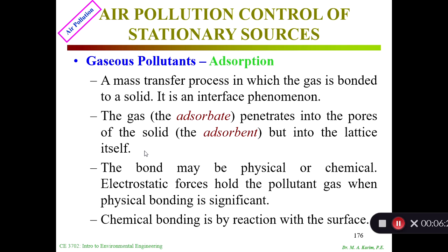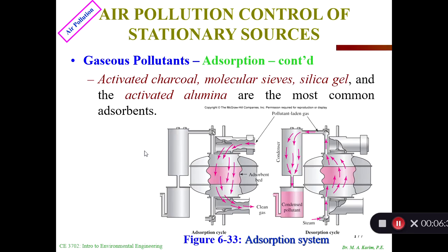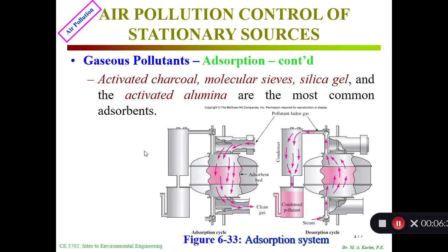The bond may be physical or chemical. Electrostatic force holds the pollutant gas when the physical bonding is involved. Chemical bonding is by reaction with the interface, if there is any. Activated charcoal, molecular sieves, silica gel, and activated alumina are the most common adsorbents.